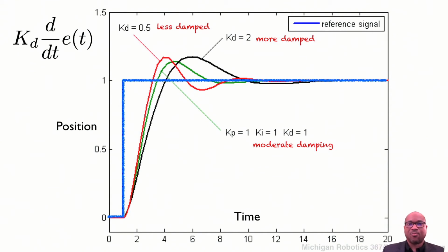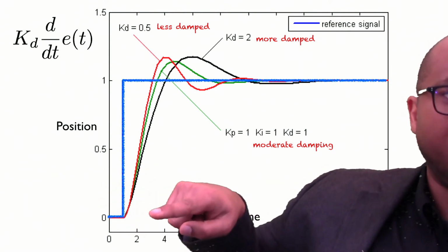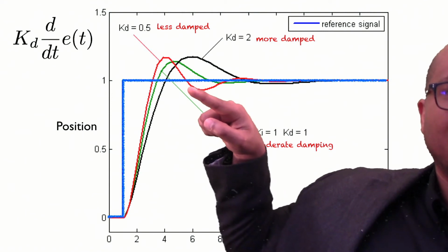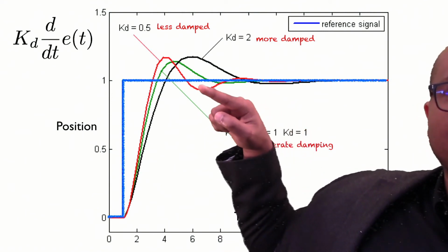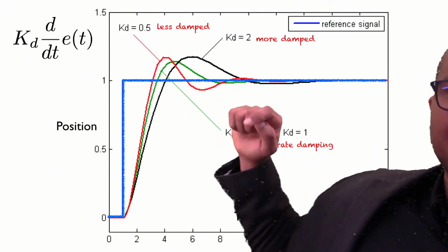If we assume our proportional term is fixed, if we change our damping, that will produce different types of profiles as we're trying to hit the set point. So in the green in this case, which my finger is trying to track, we get pretty nice behavior where we just overshoot and then we gracefully head back into the set point.